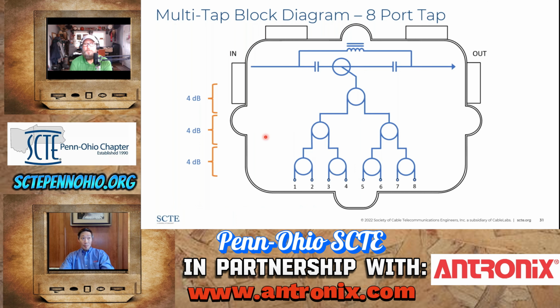So an 8-way, similarly, has an extra set of splitters. So a 20 dB tap and a 2, 4, and 8-way all have different directional coupler values because of the amount of loss that is split on each of the ports. So I think when we talked about the through loss, right, of a tap, or the insertion loss of a tap, that's largely determined by the value of the directional coupler, right?